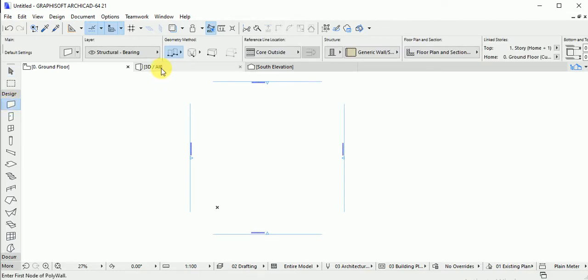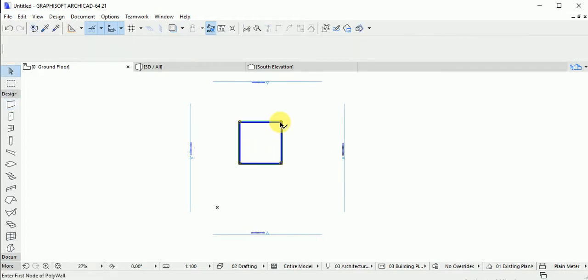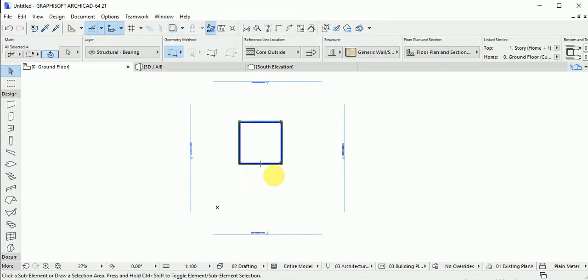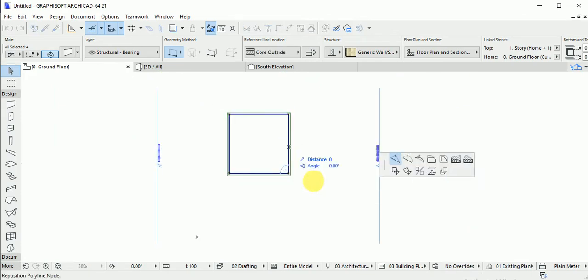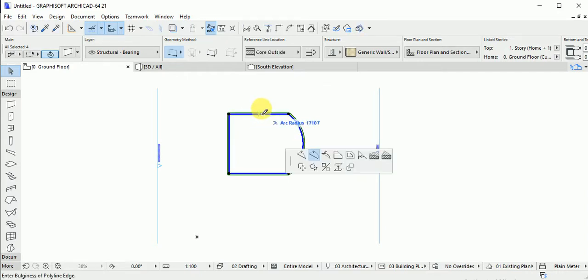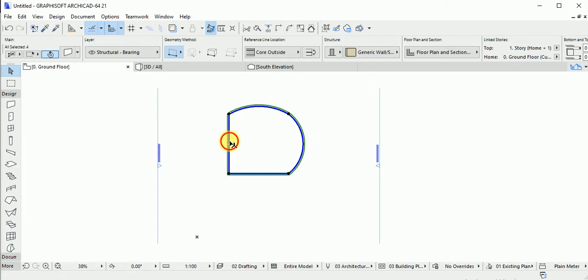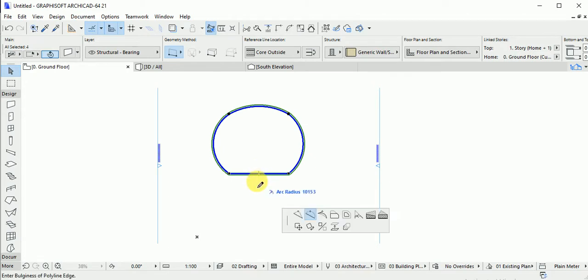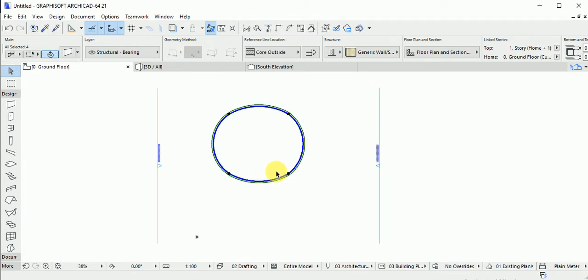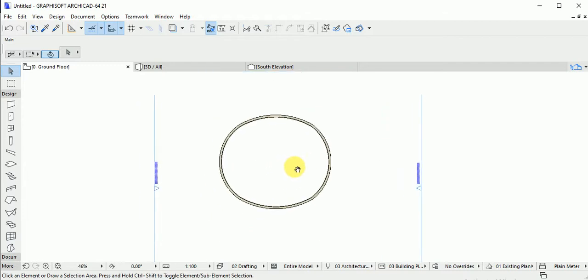Now let me assume that we have a roof, we have a wall. This is the wall that we're having. This wall now is grouped, so I'll press Ctrl+Shift+G to ungroup them. You can see it's having some slide dots. So let me assume, due to my editing, I want to make this a circular roof, not a circular wall. I want to show you something. Sometimes this is a circular wall, and you'll be wondering, how am I going to draw this particular roof?